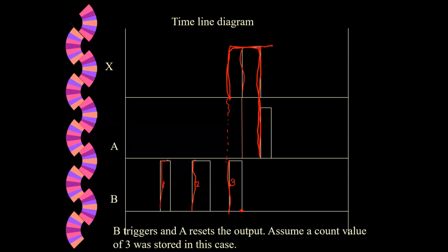Okay. Different PLCs operate differently. So you have to know how the counter works. So right now, take this diagram. When I show you the demo of the PLC of all these functions, you will see whether it is going to be triggered on the rising edge or on the trailing edge. So the rise or the trail is important. Plus, it can be a pulse. It doesn't have to be continuous.